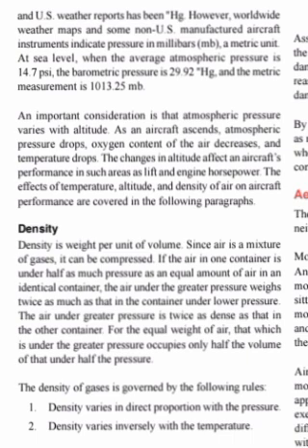The air under greater pressure is twice as dense as that in the other container. For the equal weight of air, that which is under the greater pressure occupies only half the volume of that under half the pressure. The density of gases is governed by the following rules. 1. Density varies in direct proportion with the pressure. 2. Density varies inversely with temperature.